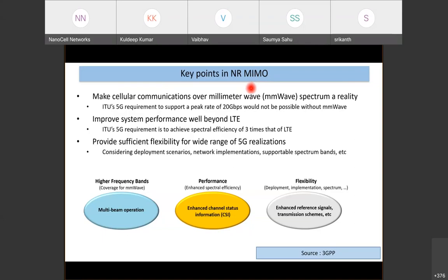And I would say its demands of an FR1 system and an FR2 system are slightly different. Remember that in FR1, we do not have as much spectrum as we would like. In FR2, we have lots of spectrum. Probably we don't have the coverage that we desire. So definitely for meeting that coverage in FR2, we have a very elaborate description of multi-beam, which is the most exciting technology-wise thing, very critical for FR2 systems to succeed.